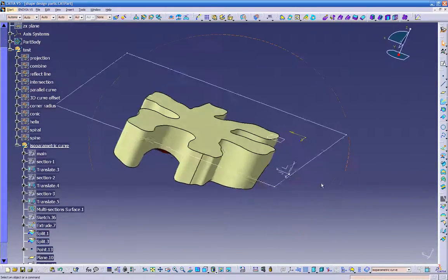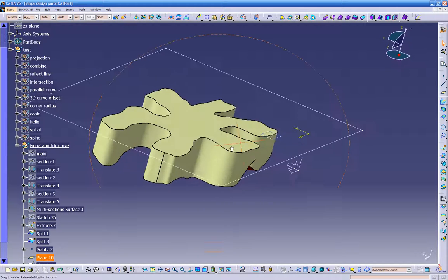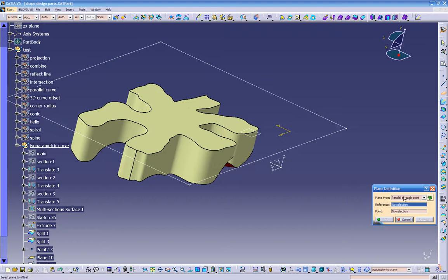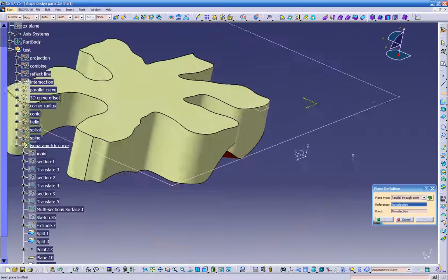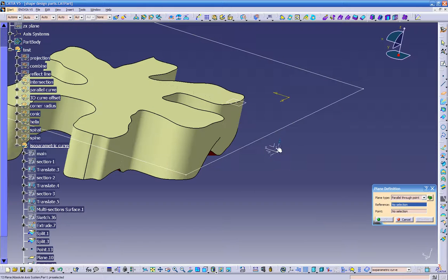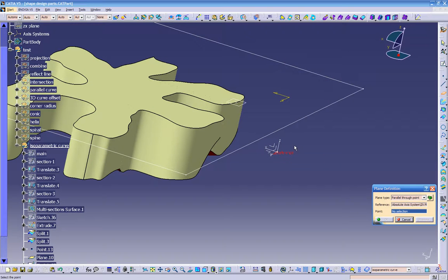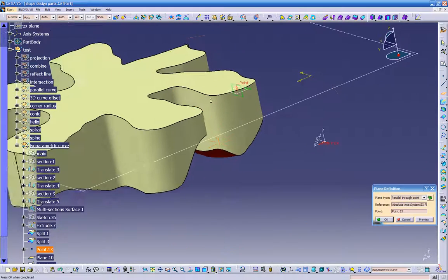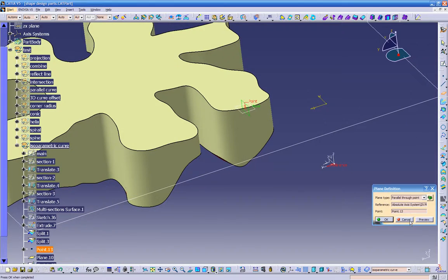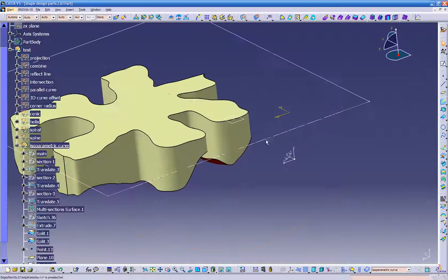That's why we have to make sure when you create the point, you click on the reference. So once again, plane parallel to a point. It's going to ask us the reference. If you say your reference is this plane right here, and then you put the point in here, watch the difference. It's going to put a point on whatever reference you just created. So we don't need that. Okay, let's turn this off.